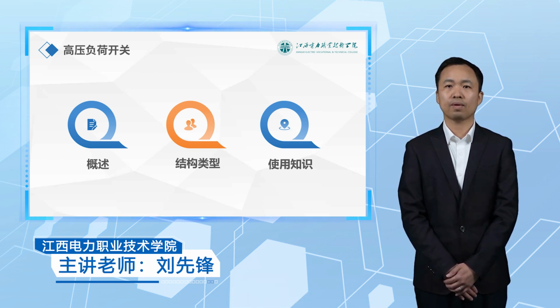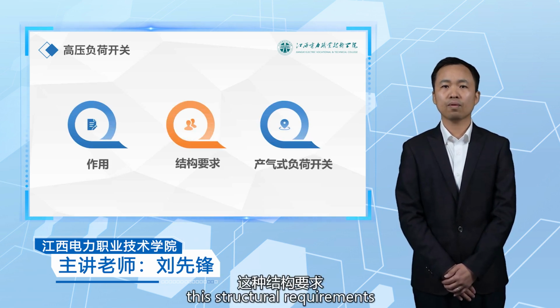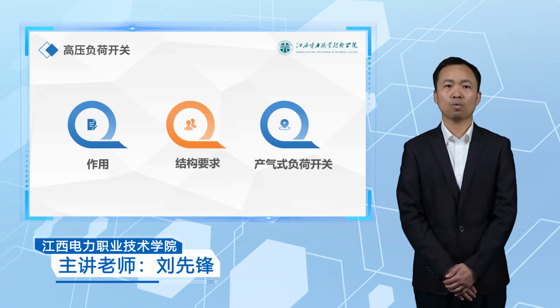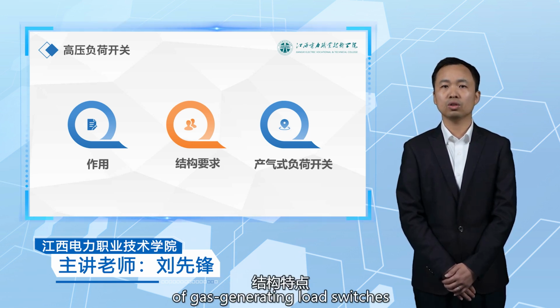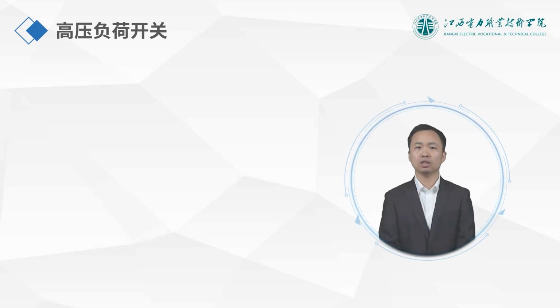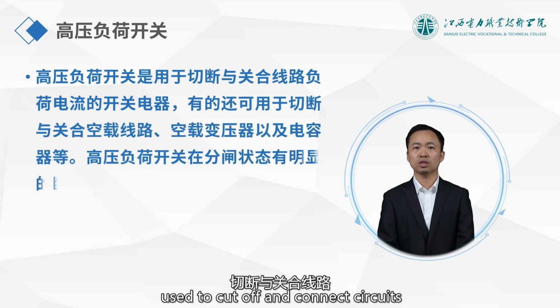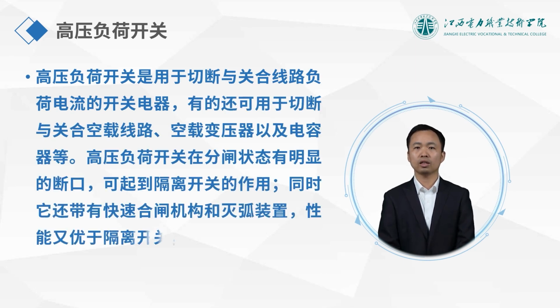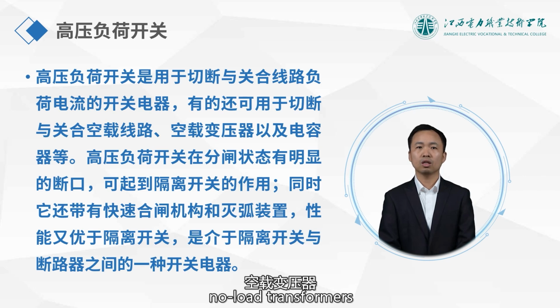In this lesson, we will mainly introduce the function, the structural requirements of high voltage load switches, and the structural characteristics of gas-generating load switches. Totally three aspects. A load switch is a switchgear used to cut off and connect circuits under load current. Some can also be used to cut off and connect no-load circuits, no-load transformers, and capacitors.